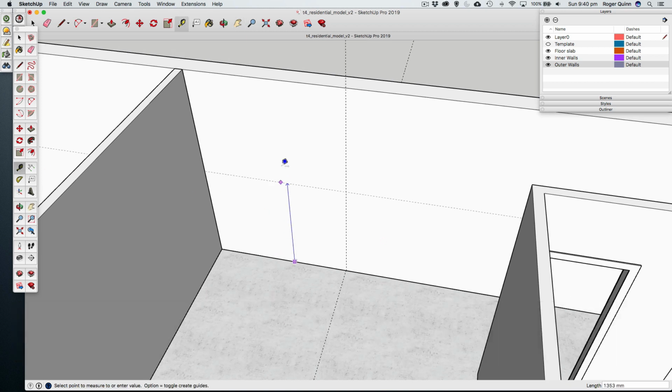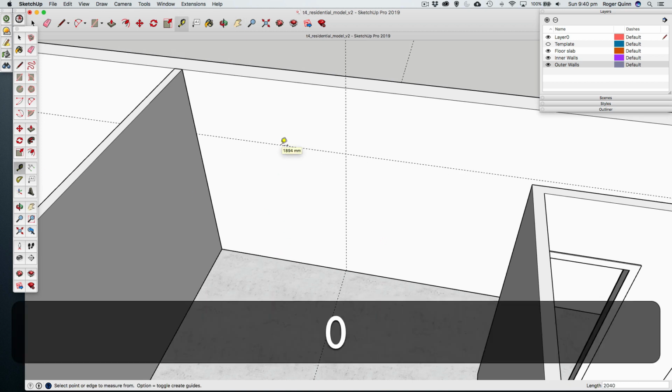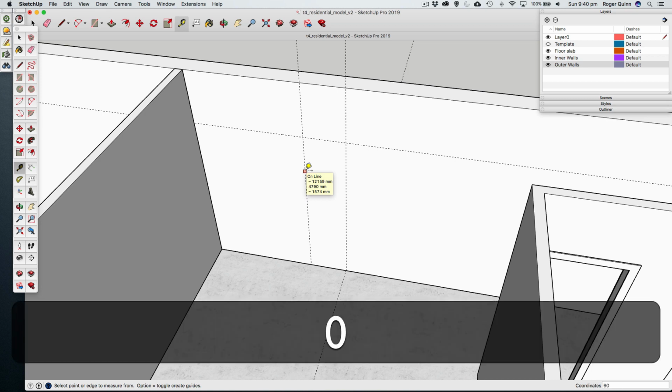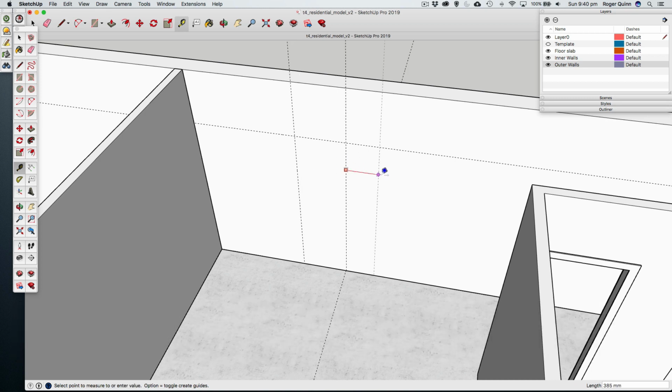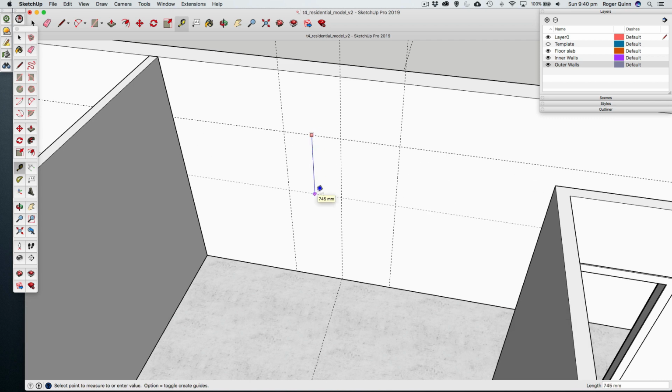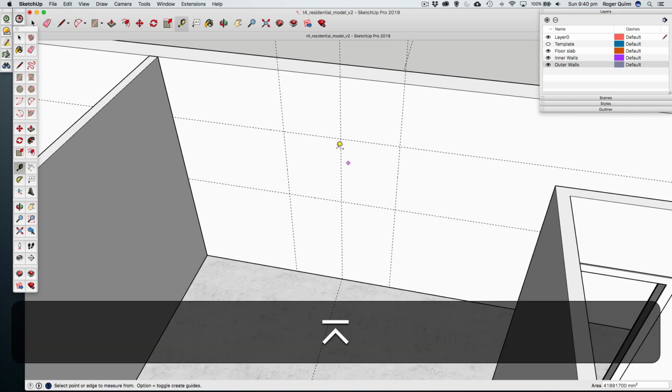In this case, approximately just putting the height there, by the way, which is around about 2040, around about a door frame height, and then I'm dragging some guides, 600 mil either side of the centre to give me a window that's 1200 wide, and then finally a guide that's approximately 800 below that to give me a 1200 by 800 window that is smack in the centre.